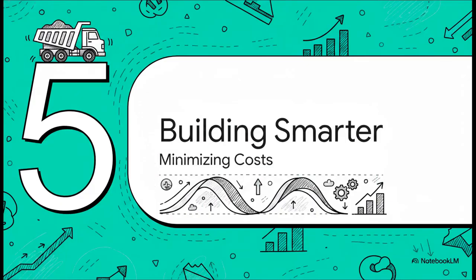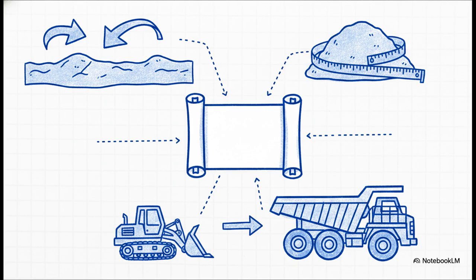All right, wrapping things up with Section 5, Building Smarter, Not Harder. So, to put it all together, the Mass Haul diagram basically dictates absolutely everything on the job site. First, it minimizes costs by telling contractors the absolute most economical direction to push the excavated dirt, like whether to drag it forward down the highway or push it backward. Second, it calculates haulage. It gives the exact, undeniable data needed to compute those expensive overhaul contracts without any guesswork. And finally, it handles equipment planning. It helps fleet managers figure out, hey, do we need massive articulated dump trucks for long hauls here, or just a few bulldozers for short pushes? It orchestrates the capacity, the travel paths, really the entire logistical ballet of the construction site.